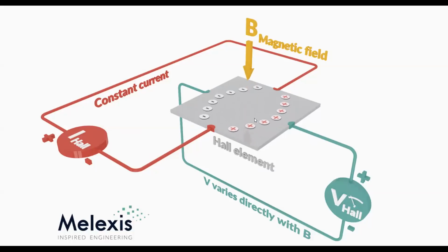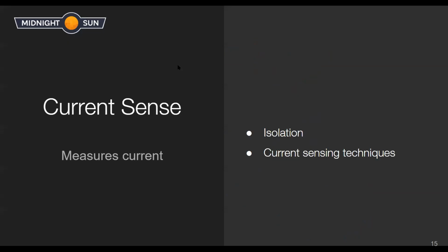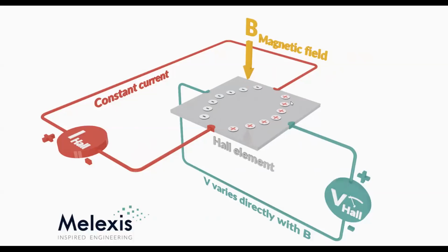So if this is a piece of metal, the positive charges don't actually move because the positive charges in metal are just atoms. But if you were using a p-type semiconductor for this, you would have holes that would be mobile. And then the charge carriers will eventually reach a point where the electric field between them prevents them from being pushed any further away.